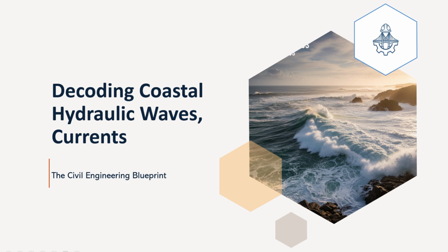This provides a simple, yet often reasonably accurate rule of thumb for predicting the breaking depth and breaking wave height. More complex criteria exist, often involving wave steepness as well. And the type of breaker matters too for how it dissipates energy and impacts the coastline and the structures we might build there, right? We mentioned spilling, plunging. Not all breaking waves behave the same way.